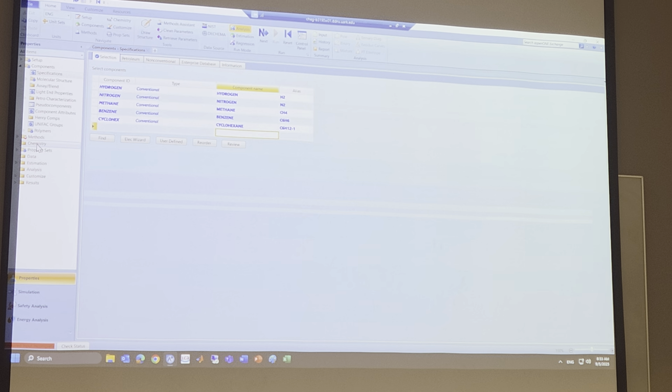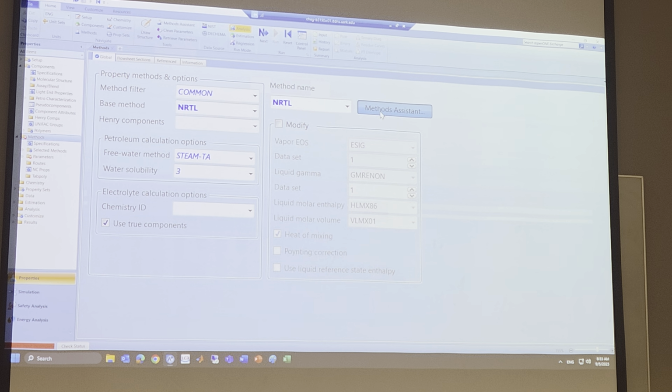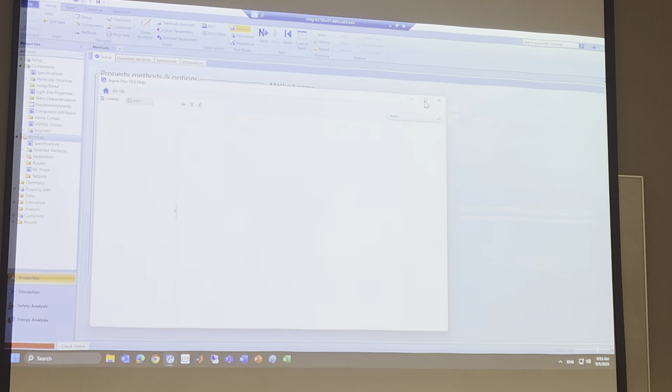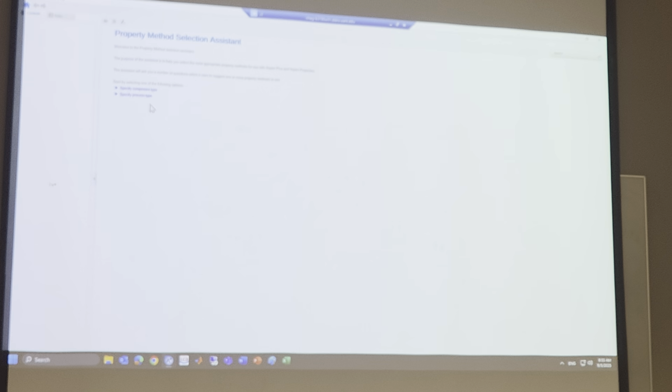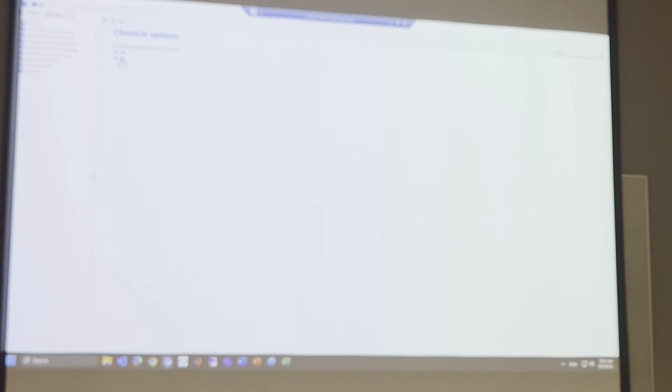Great. Next, specify the property method. If I go here, I will check the method assistant. Let's look at it. Specify component type, chemical system. We are working at high pressure today, so I will say system at high pressure.